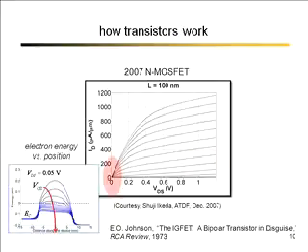The way he looked at this was that if you take a MOSFET, and we showed a cross-section earlier, we have a source, channel, drain. And if you draw an energy band diagram across the source, this is the bottom of the conduction band, and then across the channel, and then out the drain, there will be a Fermi level somewhere. Now, that tells us where the states are filled up. That's this dashed line. So in the N-type source, the Fermi level is way up in the conduction band. We have lots of electrons in the source.